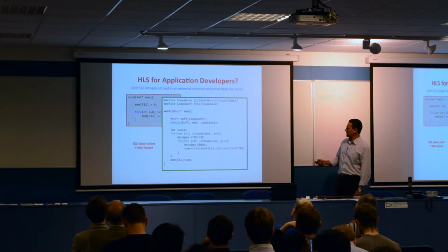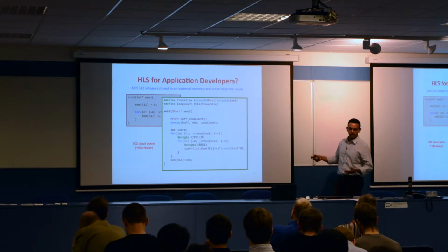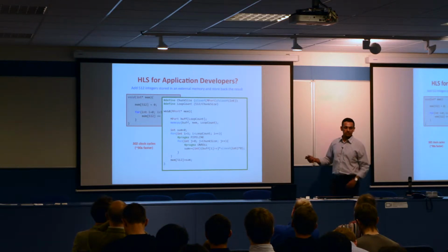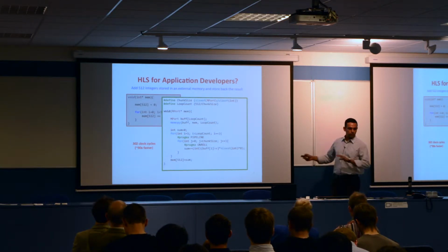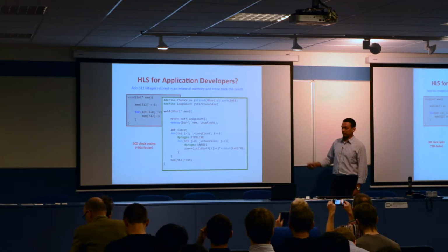Now what if I start optimizing the code? So I write a little more complex version. I start looking at the width of the memory interface, I use explicit burst transfers, I use pipelining and unrolling, explicitly saying where the parallelism exists, using local variables, all the transformations you need to do. Now the performance becomes 90 times faster, 302 clock cycles.